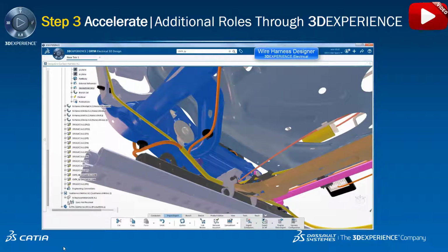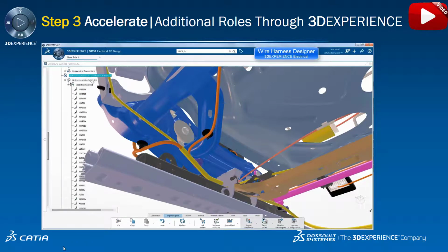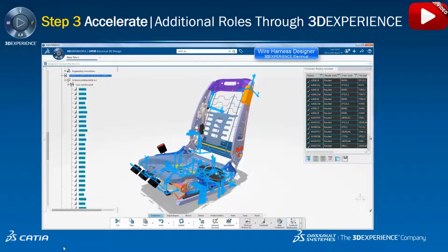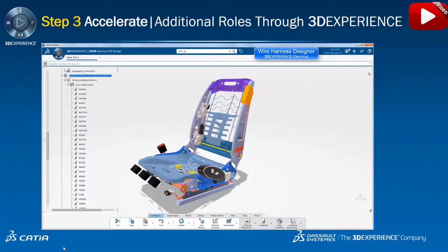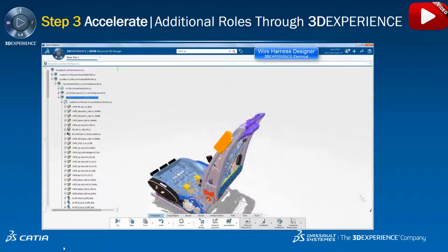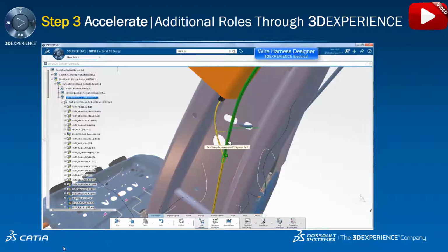an external ECAD system. We can import them so we have them in our session. They are not yet routed through the bundle, but they have a from to check, and we have a from to for every wire, as you can see here in blue. The next step is to route the conductors inside the bundles we've created to obtain the wire length and calculate the diameter of the bundles based on the number of wires inside and each wire diameter.